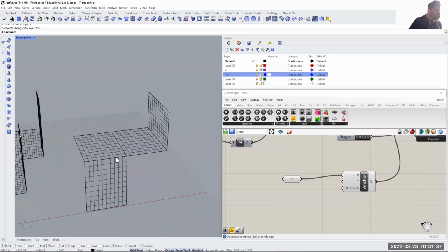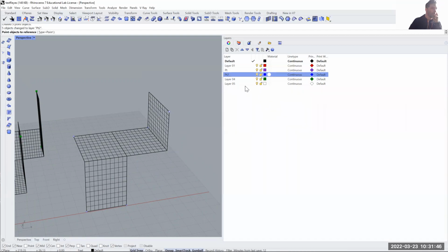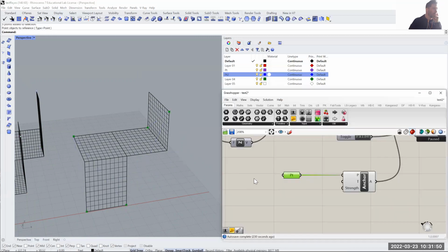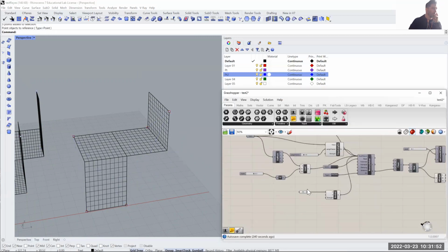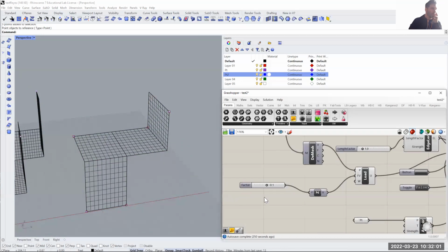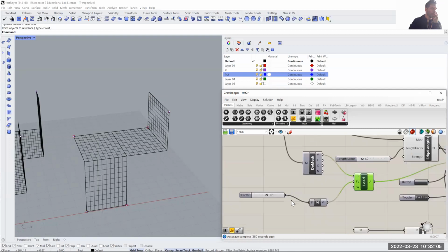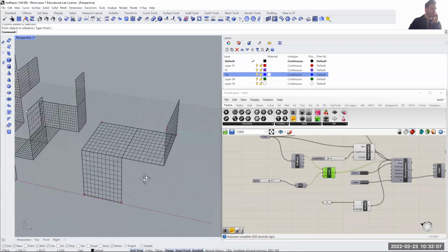When you add more points or you extract more points, you're just going to have to place them again into the anchor points definition. So you're going to say set multiple points, right click on the layer, change the select objects, and then enter, and they will be there. So there you go. So you have basically the mesh is working and the points. Again, you can work with the length factors or I have a load, a particular gravity feeling and so on.